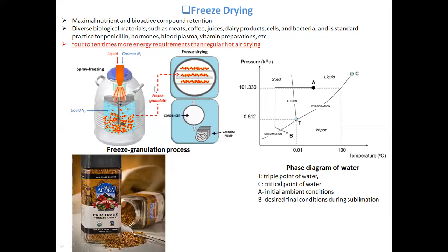But when it is exposed to this vacuum container, the granules of coffee with the moisture, or the crystals in that, will readily, because of the vacuum, sublimate, clear. The solid moisture, in the ice form, sublimates to vapor, and which is taken out from this section, clear. So such type of freeze drying is used, as I told you, to keep the maximum nutrients and the flavor of the coffee as it is. So freeze drying is the only option.